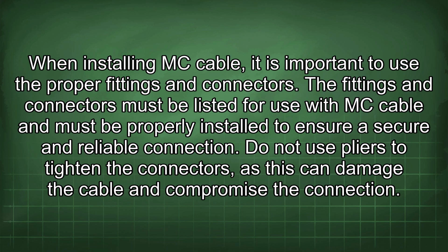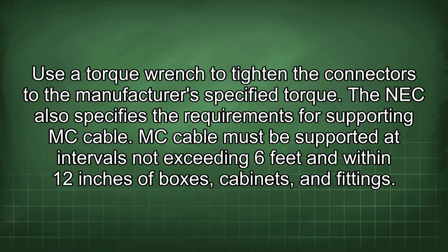The fittings and connectors must be listed for use with MC cable and must be properly installed to ensure a secure and reliable connection. Do not use pliers to tighten the connectors, as this can damage the cable and compromise the connection. Use a torque wrench to tighten the connectors to the manufacturer's specified torque.